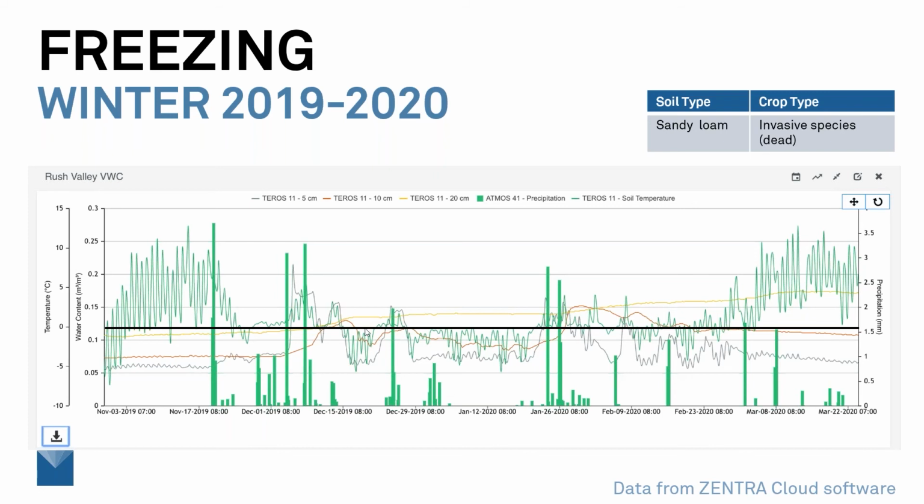And you see this green line is temperature, and every time it freezes, the water content line drops down. When it thaws, it jumps up. When it freezes, it jumps down. And now I saw this relationship between the temperature and the water content. It all makes sense to me that when water freezes, and the more it freezes, the more the water molecules themselves disappear to the electromagnetic sensor that is trying to polarize those water molecules in an electromagnetic field. And so when they disappear to a greater or lesser degree, then we see the water content drop down.